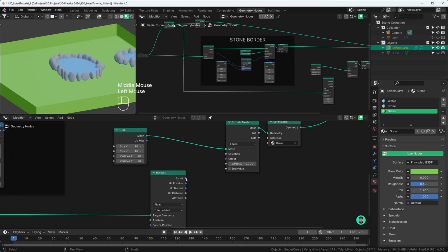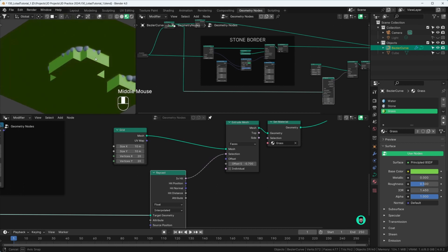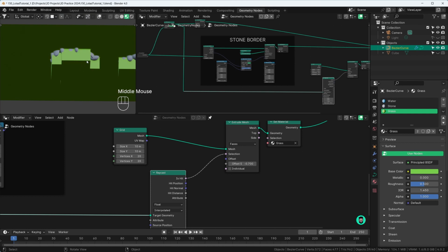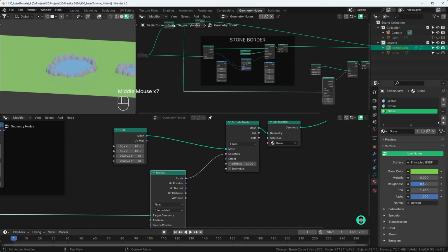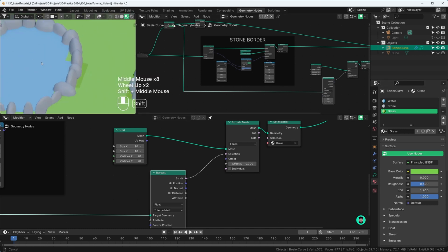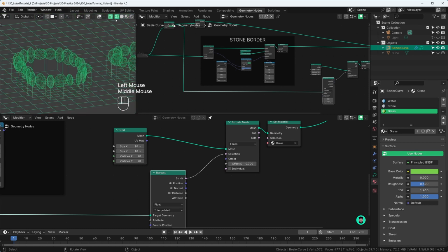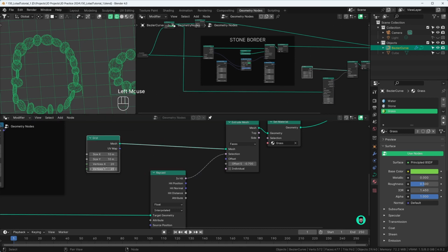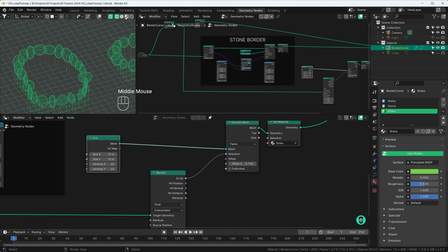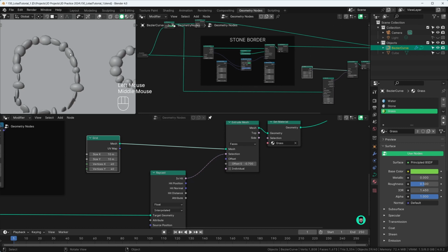So let's connect this is hit into the selection and you will notice that something just happened. So if you see it from the bottom face, you will notice that now only the pond area is being targeted and extruded downwards. So that is exactly what we want, but it does not look very good because we have these very weird shapes going on. This is due to the grid size. If you go into the wireframe mode, you will see that it takes only the edges to calculate the extrusion because of how geometry works. So let's take the grid and turn up the vertices to 40 by 40. Now it's a bit more fine mesh, so you will notice that we have some better looking edges.